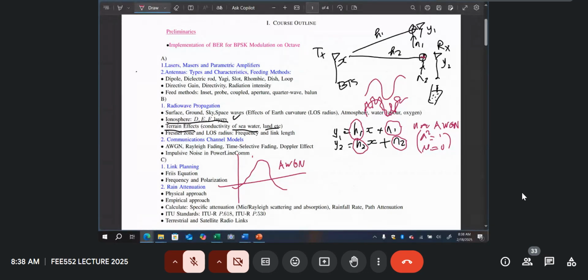So the PDF, so variance 1 and mean 0. So you can have, if you have, so that we normally leave noise as additive white Gaussian noise. White, the distribution of power is the same for all frequencies. That's what it means. Gaussian, it means it is bell-shaped, right? The additive is because it's added onto the signal. So that's why we call it so.